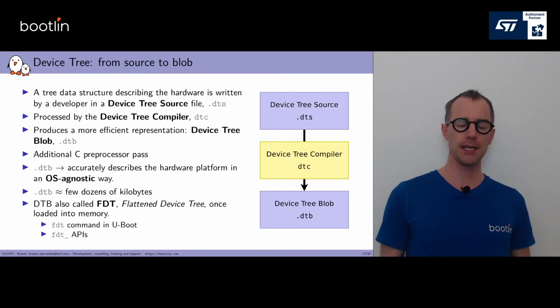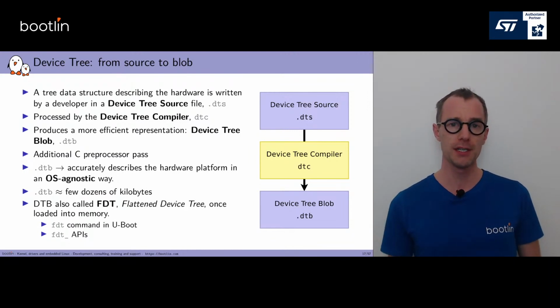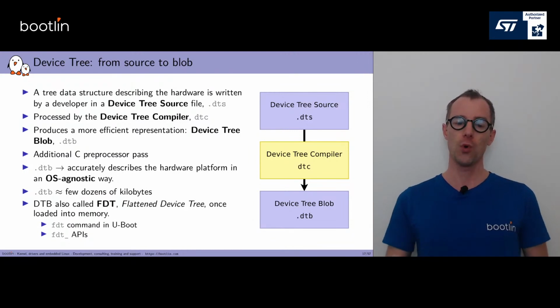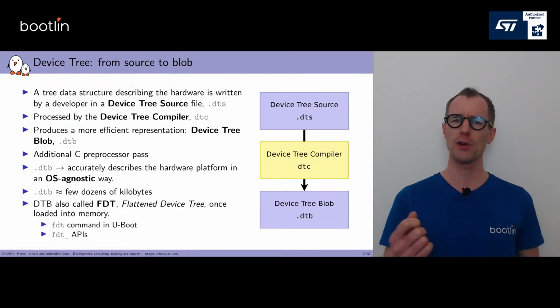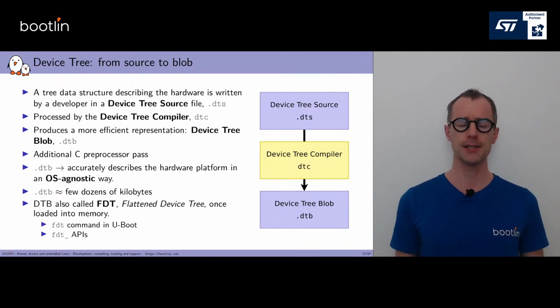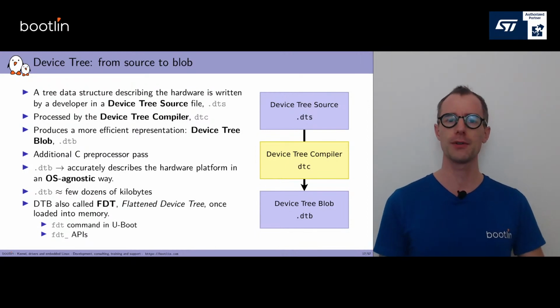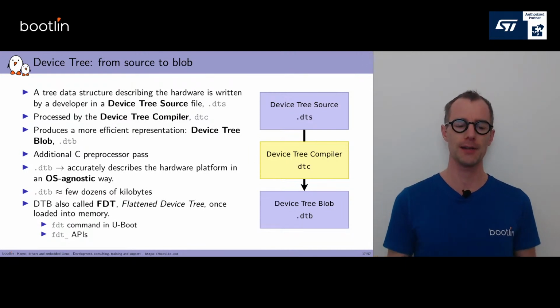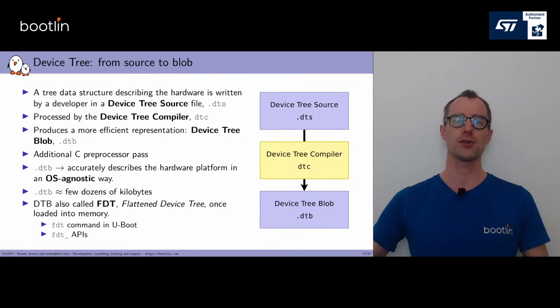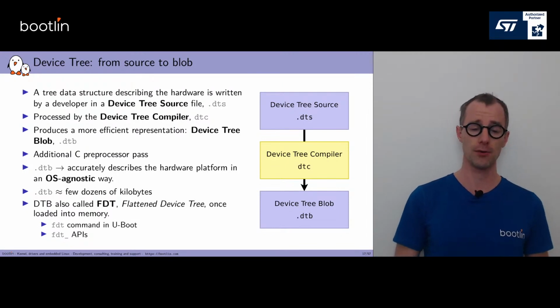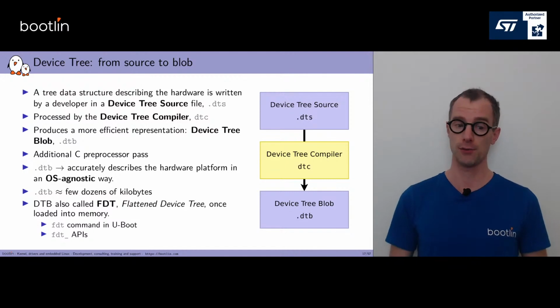This DTB is also sometimes called FDT for flattened device tree, once it is loaded into memory. So you will find in different places, like in U-Boot, there are some commands named fdt for flattened device tree to manipulate the device tree. There are APIs named fdt_something that also exist. So that's why I insist on that terminology as well.